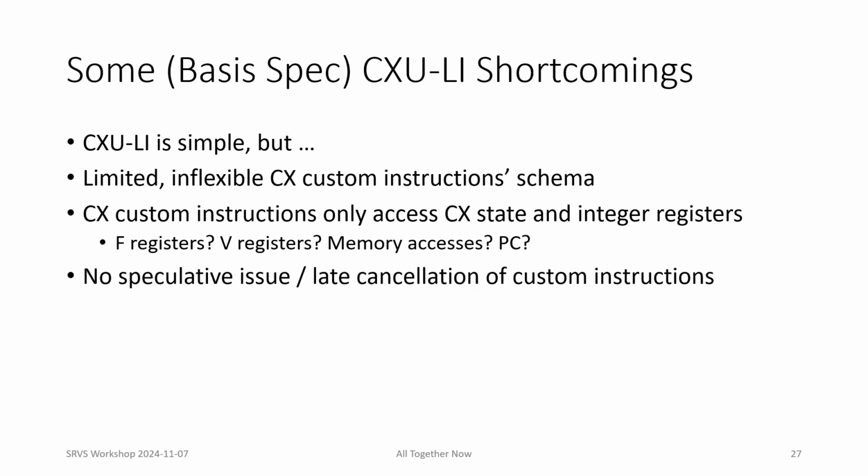Also, there's no support for speculative issue and late cancellation of a custom instruction. So for precise exceptions, a CPU must hold off issuing a custom instruction CXU request until it can establish that no prior instruction will raise an exception.